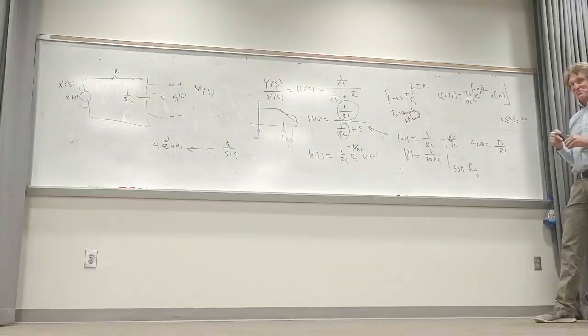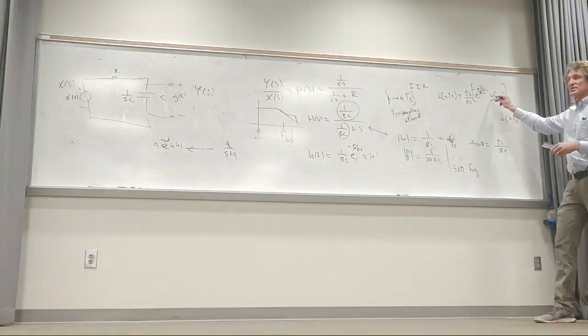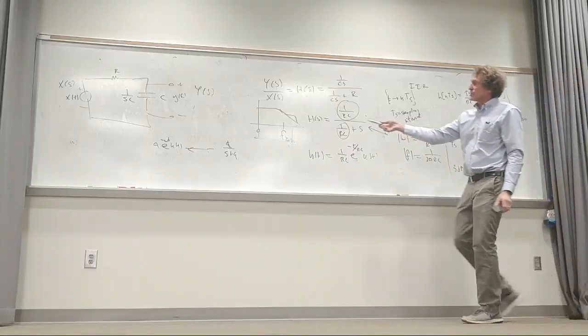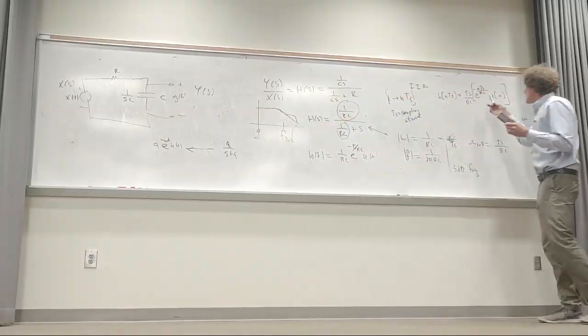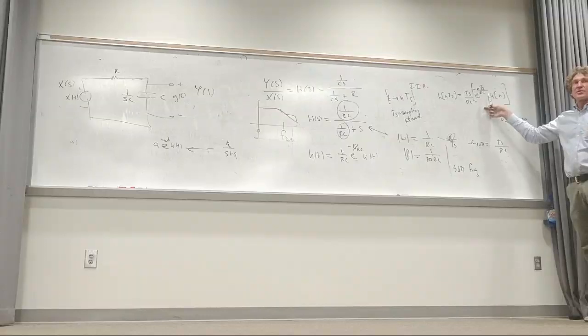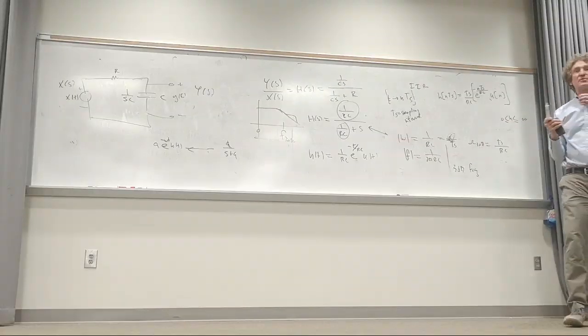Do you remember that? Kind of, sort of? Yeah. All right, don't worry about this much of it. What I'm really getting at, when you have this, how many dB of roll-off was that? 20 dB, right? Now think about this. I can adjust the value of RC here so that the 3 dB frequency would be the same as the frequency we had for the original filter.